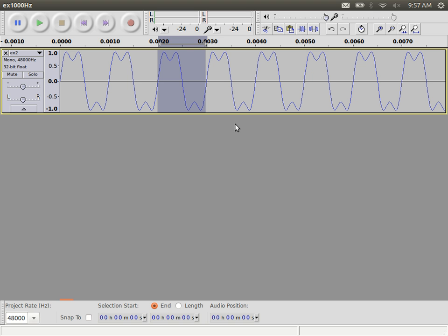Therefore, in 1 second, and you could count them if you wanted to, 2000 bits. So the data rate we can achieve with this signal is 2000 bits per second. Let's make note over here. We could achieve a data rate of 2000 bits per second with this signal. What's the bandwidth of our signal? What's the bandwidth of the signal?